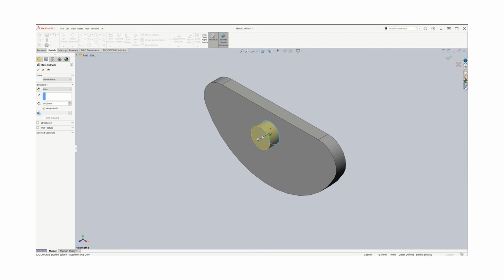Instead of having your object extrude in this direction, I want the other direction, starting from that surface. In that case, without creating new features, you could do it this way. I could use offset, or you could choose the surface from, so I could choose the surface right there.